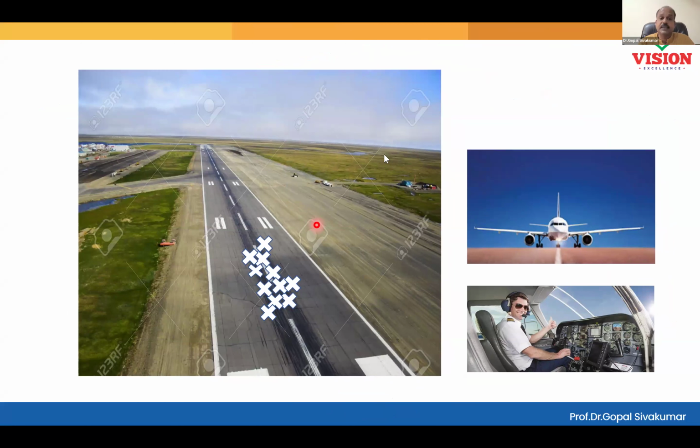Suppose my car size is half the size of the parking area and my driving skills are not influenced by spouse or boss or any surrounding, I am able to focus properly. That means the SOPs, whatever recommended, is being practiced in the shop floor. Very rare scenario, isn't it? Whatever SOP is created, people follow exactly the same. And now your car is at the center. Your car is half the size of the parking area. Now you are creating a scenario known as doubly capable. CP/CPK will be equal to 2. Pick up the CPK, multiply by 3. 2 into 3, 6. 6 sigma capability.